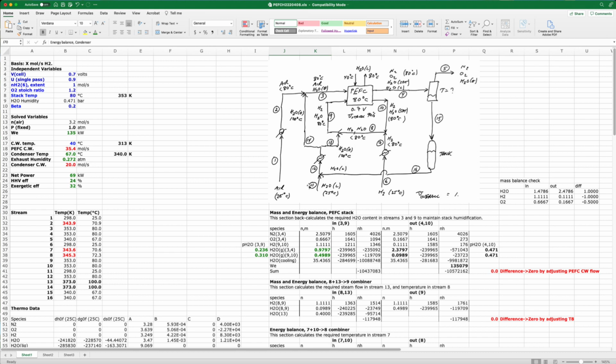So this is not always the case. Sometimes you might have access to water at all times, and so you don't have to worry so much about water recirculation. But for mobile transportation applications or applications where you have a fuel cell that's not readily connectable to a water supply, it's very beneficial to try to eliminate stream 11 and recirculate, use all water that's completely recirculated.